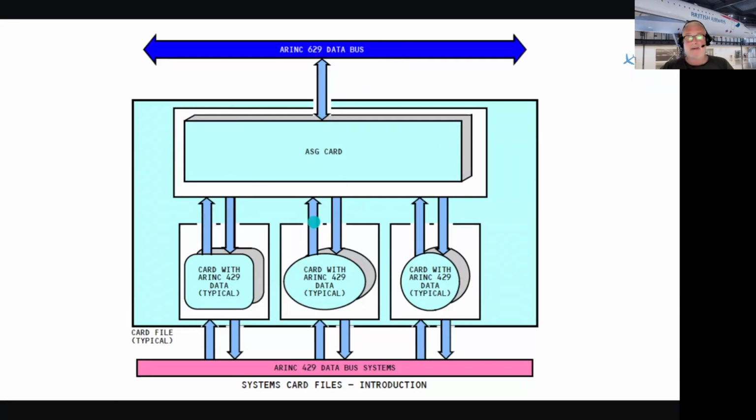Unlike the Arinc 429 data bus, where you have all the systems here for the data bus, and you then have 2 cables, one, as it's unidirectional, a transmit and a receive, for each LRU. So look at this: 1 cable, multiple cables.